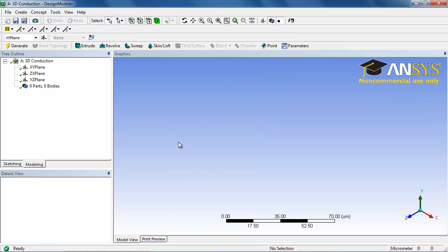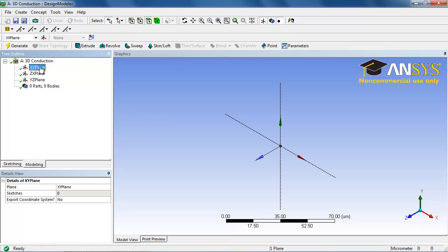Now, we have 4 parallel planes on which our materials sit. We can either create 4 planes and model them as a positive extrude, or, easier, we can just create 2 planes and extrude in the positive z direction and the negative z direction. So I will place the 2 planes at the 2 borders: the silicon and silicon dioxide border, and the platinum and the water border.